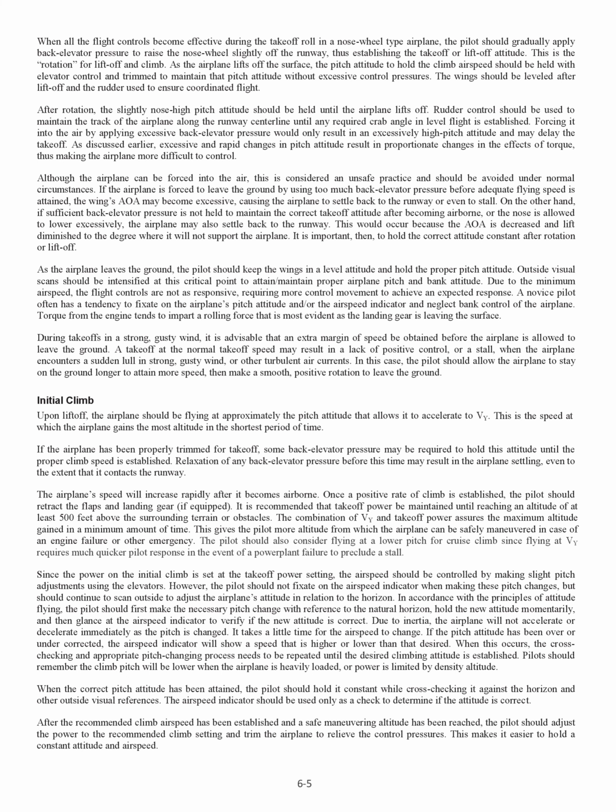Pilots should remember the climb pitch will be lower when the airplane is heavily loaded, or power is limited by density altitude. When the correct pitch attitude has been attained, the pilot should hold it constant while cross-checking it against the horizon and other outside visual references. The airspeed indicator should be used only as a check to determine if the attitude is correct.